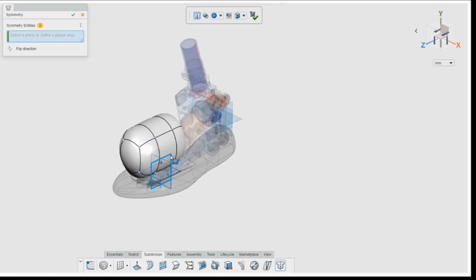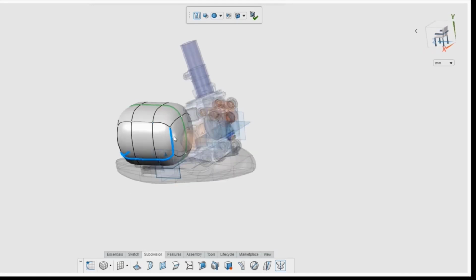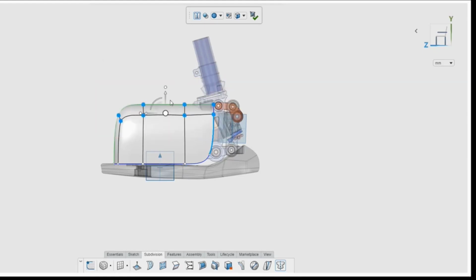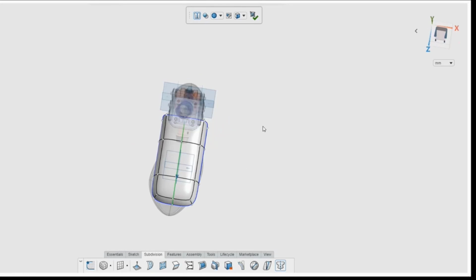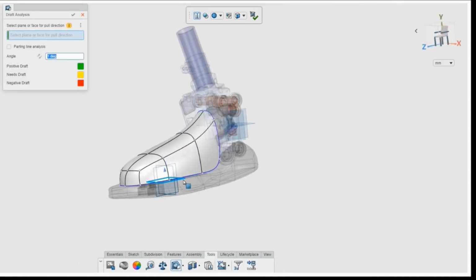And you can even use all the nodes and the curvatures with respect to the symmetry. You can drag them and align it according to the curvatures like this, right? Now, by using the push-pull method, you just adjust it with respect to the backend reference assembly. And one of the most advanced tools is this one, that is Quick Align. So you can simply drag a line. According to that, your entire primitive shape will be adjusted, right? Now using all the nodes, you can simply drag your points and nodes and adjust it.